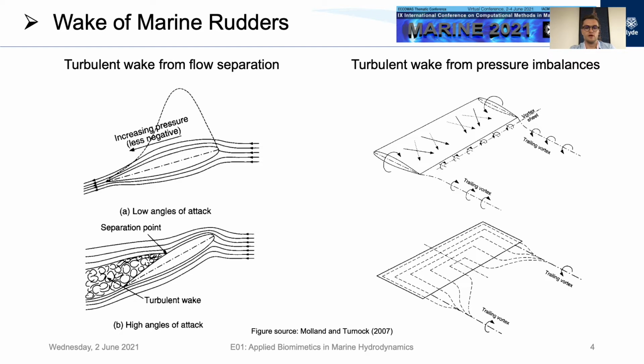This is especially relevant to finite span foils such as rudders, as the tubercle leading edge could reduce the buildup of the trailing edge vortex sheet and the resulting distinctive tip vortices. Vortex interaction between the tubercle vortex pairs and the tip vortex might have further reducing effects on the tip vortex. Minimizing the turbulent wake is important, as its vortical structures cause drag, increase flow noise, and add to the non-acoustic signature that's detrimental to submarines, for example.